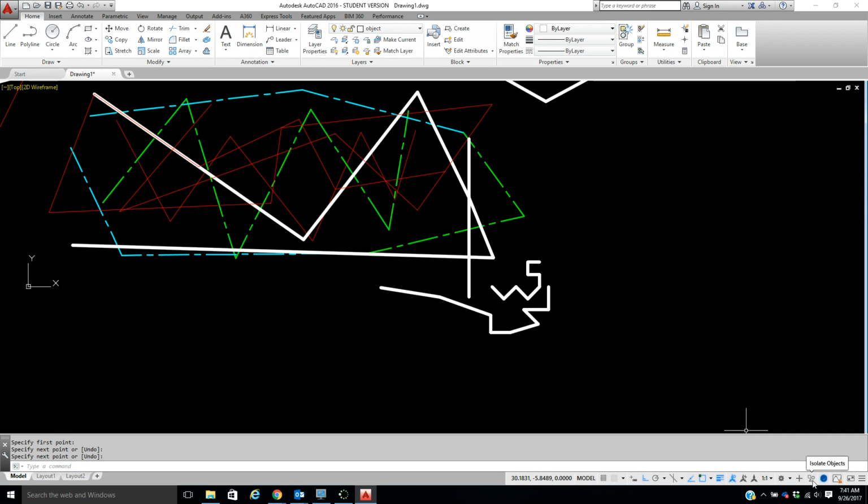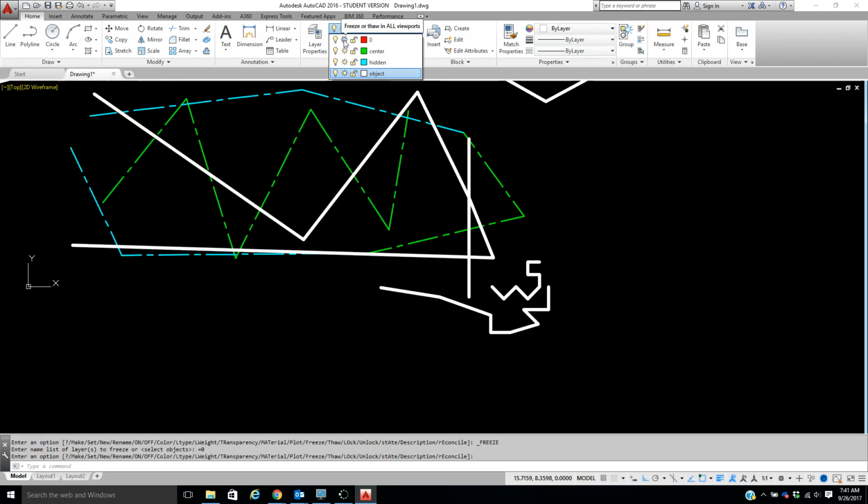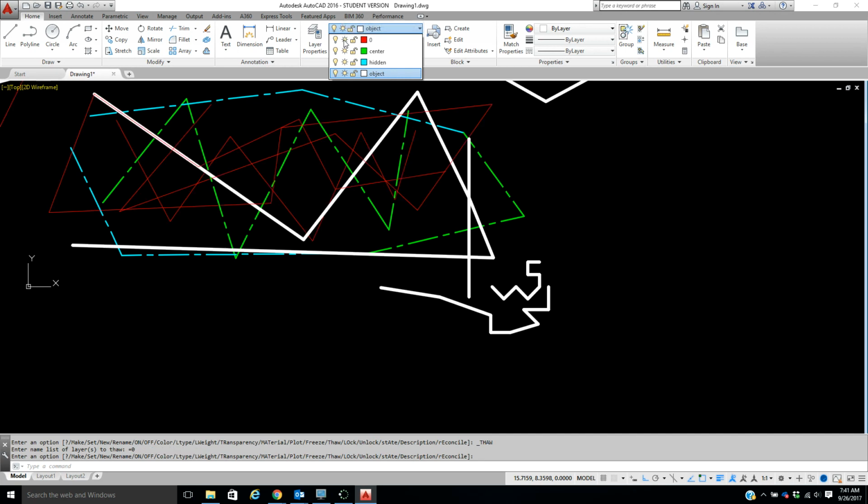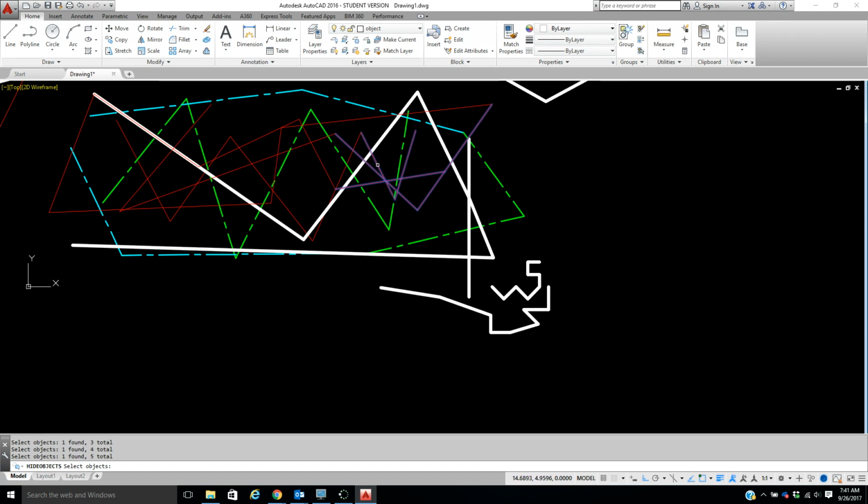This little guy right here is super helpful. I know you use things with objects, but what if, up in this layer area, you needed something in the red, but you needed just 1 or 2, you didn't need all of them. If we froze it off, we couldn't see them. But if we come up to here, we can go isolate or hide. If I say hide, I can say, okay, you know what? I want to see just a couple of these red lines, and these red lines I don't want to see. These are in my way. I can choose the ones I want, right click, they're gone. I didn't erase them, they're just gone. I come back here, end object isolation, they're back.